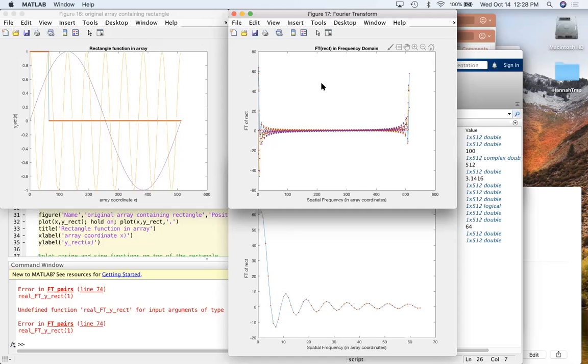Right. Okay. So one of the things that is often done is that instead of plotting it this way, which is just the raw array after that sum has been done, that formula sum, you can use a function called FFT shift, and it'll basically plot the data on this side, and this stuff it will put over here on this side. You still have the same width of frequencies represented, it just looks a bit better, right? And that's called FFT shift.